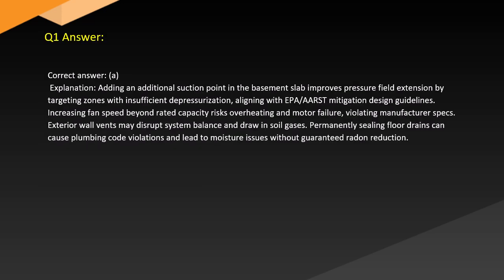Answer. Correct answer: A. Explanation. Adding an additional suction point in the basement slab improves pressure field extension by targeting zones with insufficient depressurization, aligning with EPA mitigation design guidelines.